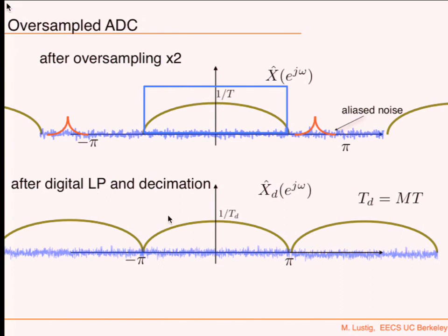Okay. So now I get a signal which doesn't have the interference in it. It doesn't have noise aliasing in it as well. And so I get exactly what I want. Okay, so by oversampling, I'm trading off that, so I need to have a faster analog to digital conversion. I can use a crappier anti-aliasing filter, and then still sample at an oversample rate, then digitally filter. So I split my system into two now.